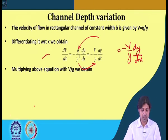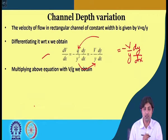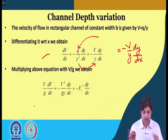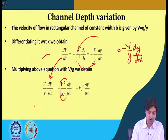If we multiply the above equation by v by g, we are able to obtain v by g dv dx on the left, and on the right this will become minus v square by gy dy dx, and this v square by gy is Froude number whole square.